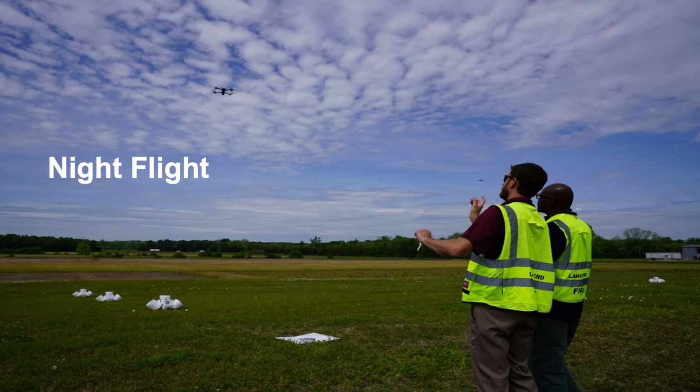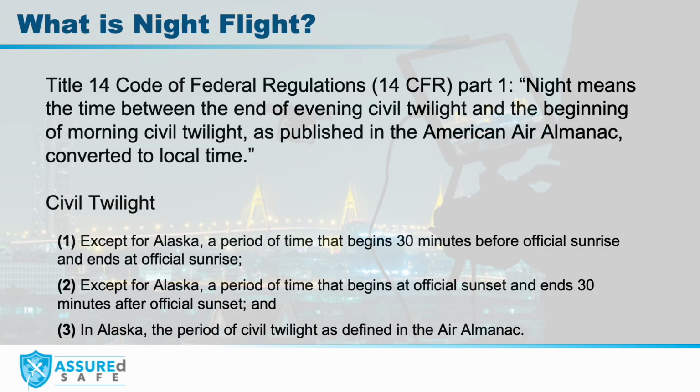As of 2021, you no longer need to apply for a daylight operations waiver to fly a drone at night. Flying at nighttime takes practice and adds additional nuances for consideration. It definitely takes more planning. So what does flying at night mean? Night means the time between the end of evening civil twilight and the beginning of morning civil twilight, as published in the American Air Almanac, converted to local time. What used to be civil twilight is now considered nighttime operations. An easy way to think about this is sunrise to sunset is daytime, and sunset to sunrise is nighttime.